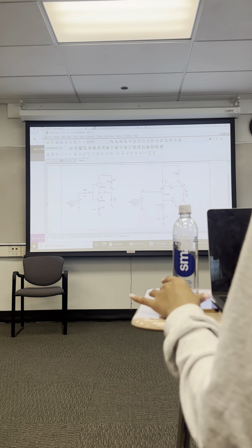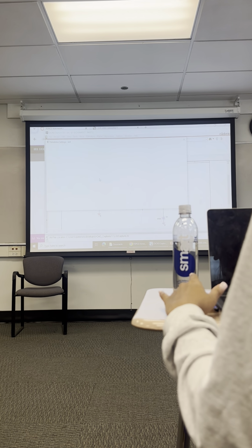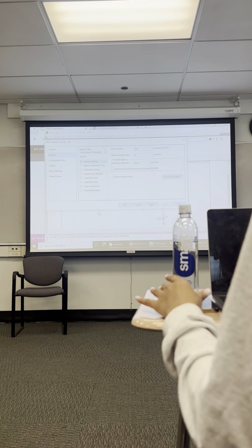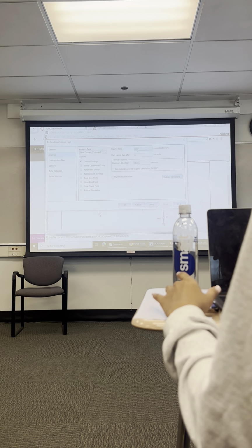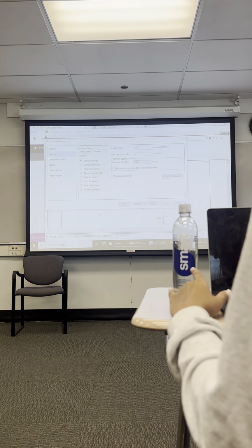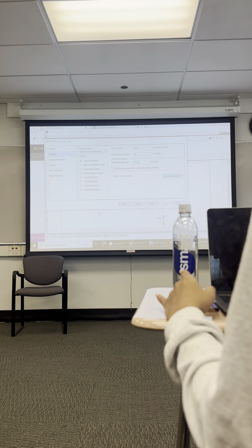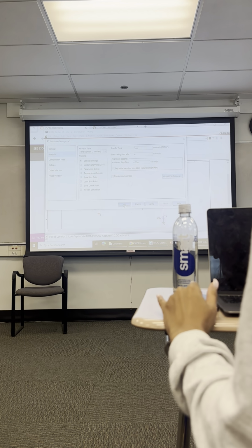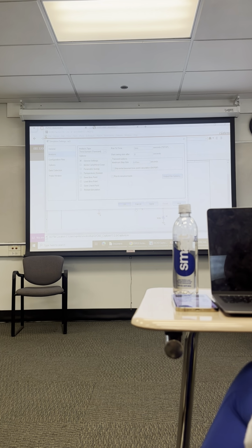So on the simulation profile, I've set up a transient. 3 milliseconds should capture 3 or 4 cycles of the 1 kilohertz, and then we use a very fine step size, 1 or 2 microseconds. Again, you decide on your result how you're going to actually do that.